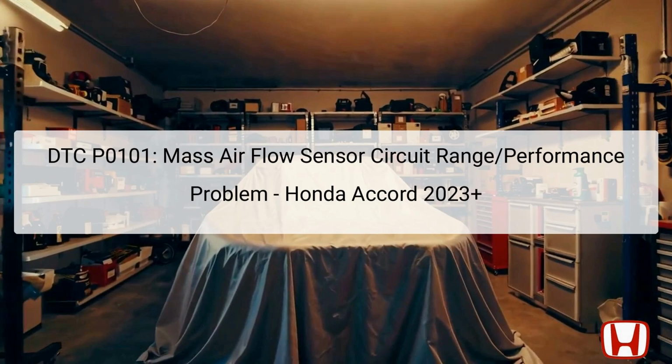The DTC P0101 refers to a mass airflow (MAF) sensor circuit range performance problem. This code indicates the engine's powertrain control module, PCM, has detected that the output frequency of the MAF sensor is outside a specified range. The MAF sensor plays a vital role in measuring the amount of air entering the engine, which is crucial for the PCM to calculate the correct fuel mixture for optimal engine performance. A malfunctioning MAF sensor can lead to reduced engine efficiency and increased emissions.